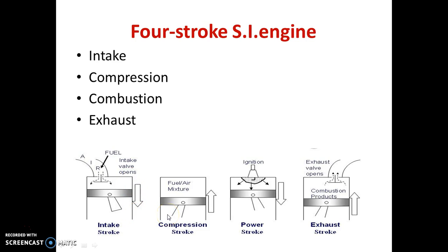Then in a compression stroke, fuel and air mixture is compressed to very high pressure, during which the piston is moving from bottom dead center to the top dead center. In a power stroke, the fuel air mixture is ignited by using the spark plug, during which the piston moves from top dead center to the bottom dead center.